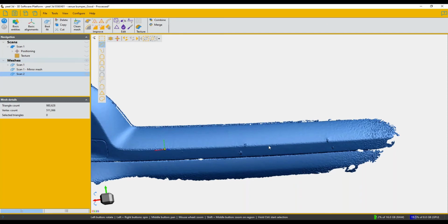I'm going to accomplish this by creating two planes first on the surface of my model. I'm going to create one on this face here, and then I'm going to create a plane where this edge is coincident with the plane, and then I can orient my part so the XY and the XZ pattern plane align with those two reference planes. Thankfully, the Peel software has some fantastic tools to help us with this.